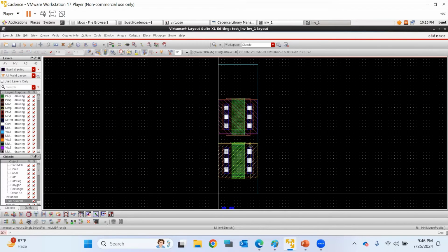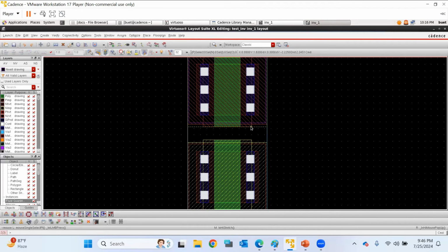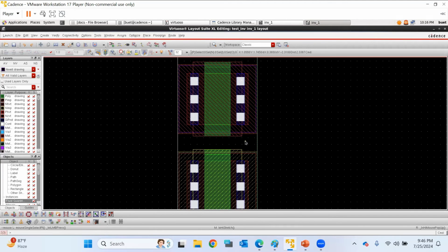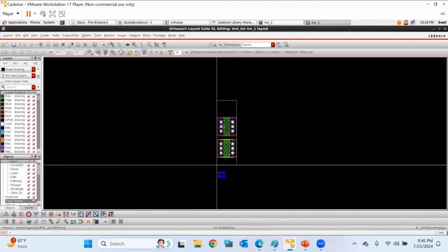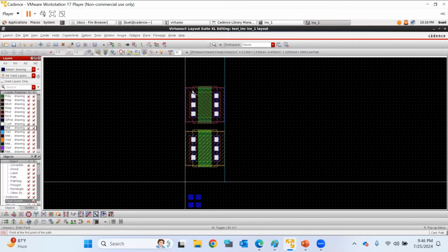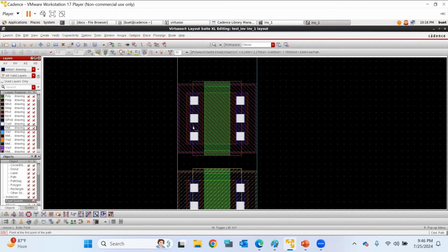So these are the two devices. As per the DRC, it should be aligned properly, which is the half DRC. Now, if I run the half DRC and I get an error, it is not good. So these are the devices. Now I take a metal one connection here. I draw one here. See, this is the VDD connection going to the top.